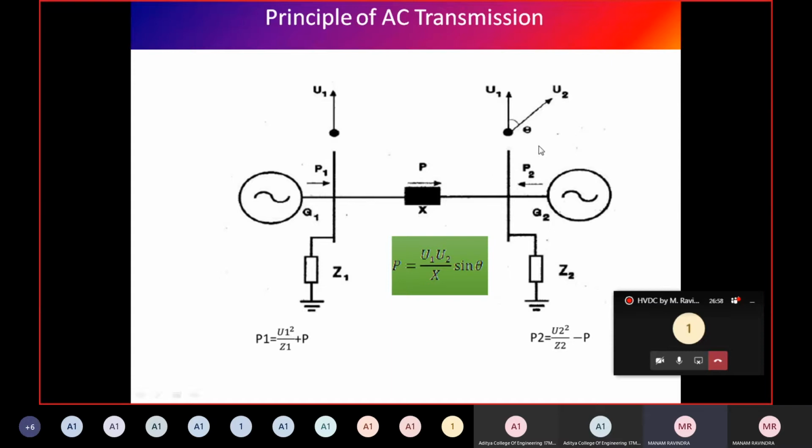Okay, stability problems depend upon the phase angle stability, and also we have uncontrolled voltage here. It depends upon the reactance values, resistance values, conductance values, and parameters of all these transmission lines. It all depends in case of the AC transmission system. If you go for large power, if you want to transmit over large distances, these are the main problems in AC transmission systems.